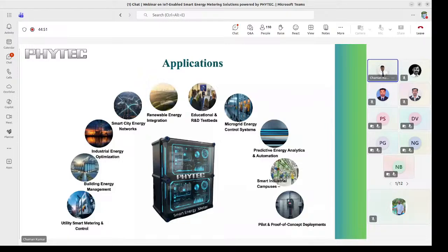And now if you go for cellular technology, in cellular we have Indian standard IS 16444. I already discussed it at the start. So here if you see, in the meter we have a cell tower. In cellular we don't need any external DCU, so you can directly send the data. But the disadvantage is, suppose the metering cost is one thing, you have to pay the running cost also. If you put in the 4G module, the SIM is there, so that running cost is also there.